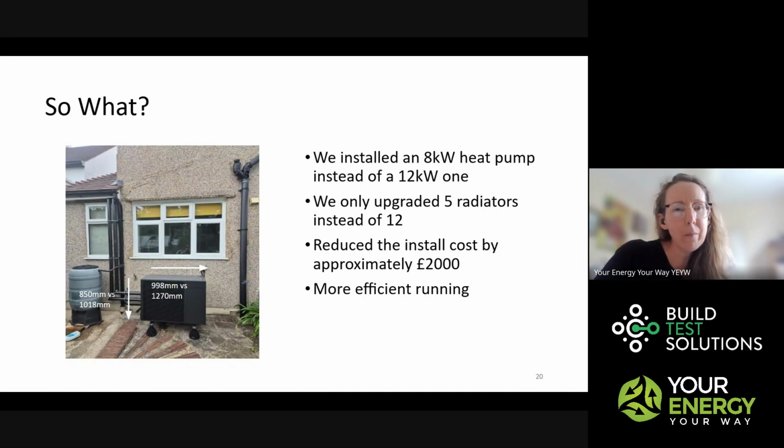And I think this for me illustrates one of the issues that we'll kind of get to, which is that we don't, as installers, often manage to close the feedback loop. So we go to a house, we install a heat pump, the customer's hopefully happy, customer's warm, we go back, we service it, everything seems to be running okay, but without having monitoring. Now, you can monitor heat pumps, obviously, but if you want to do it actually really properly, then you need to install something like Open Energy Monitor, which has a reasonable cost associated with putting that kit into the home.